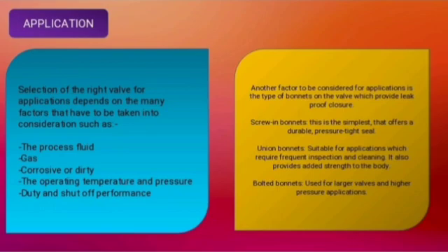Now for application. Selection of the right valve for an application depends on many factors that have to be taken into consideration, such as the process fluid, gas, corrosive or dirty, the operating temperature and pressure, duty and shut-off performance. Another factor to be considered for application is the type of bonnet on the valve, which provides leak-proof closure.